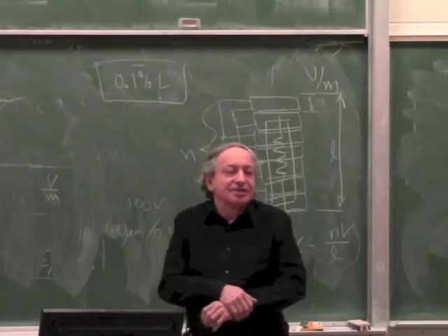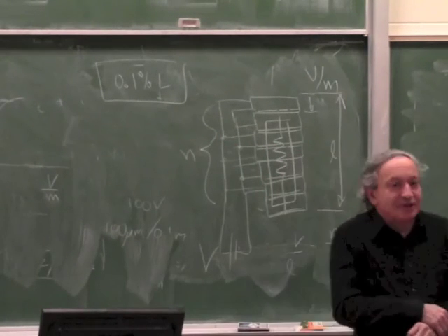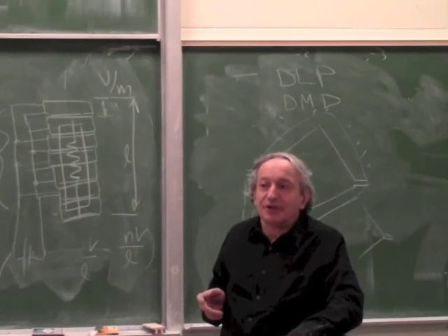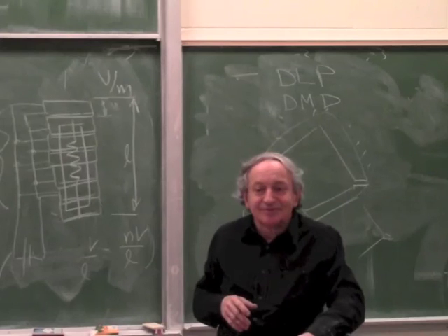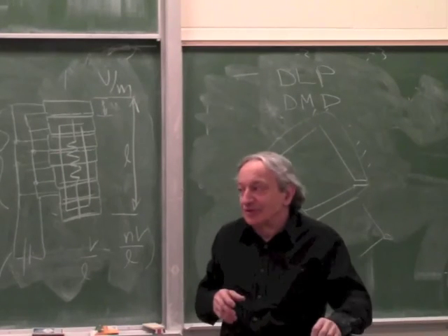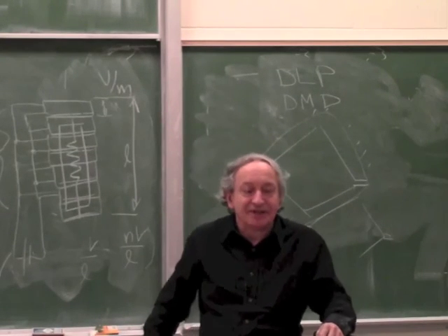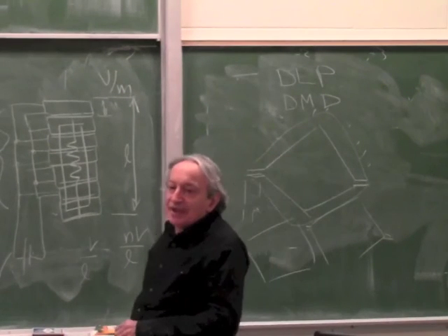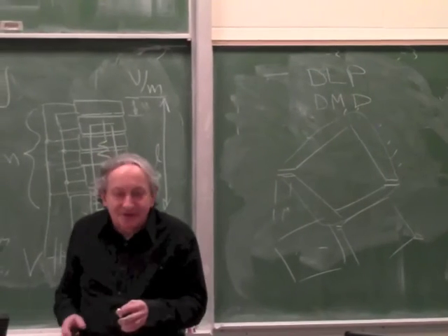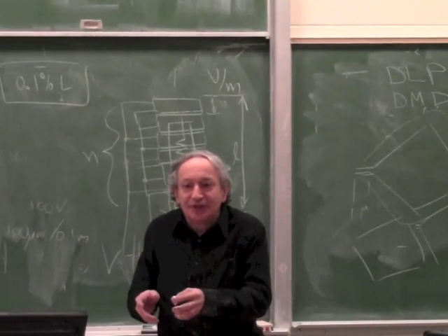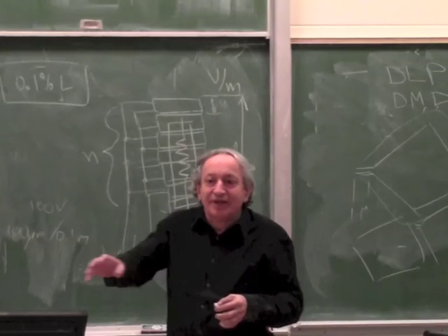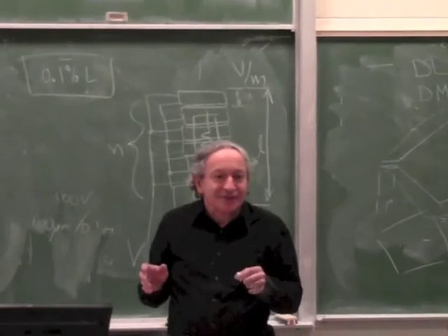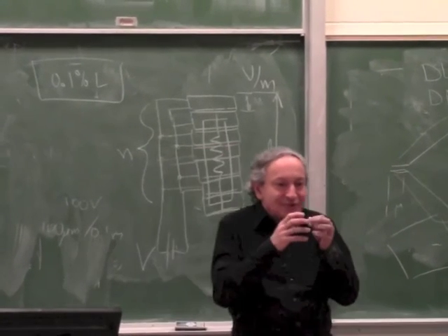Good. Now, there are many other types of actuators, like I mentioned before, hydraulic actuators. Hydraulic actuators are very good because you can make huge forces in small spaces, because the pump can be somewhere else. So if you have a very confined space and you have to generate tons of force, the best actuators are hydraulic. That's the reason why in a lot of operations where a person has to go into a tight spot, like salvage operations, rescuing people from a wrecked car, or going into a tunnel to rescue people, all the motors are hydraulic. Because in a very, very small package you can put huge power.